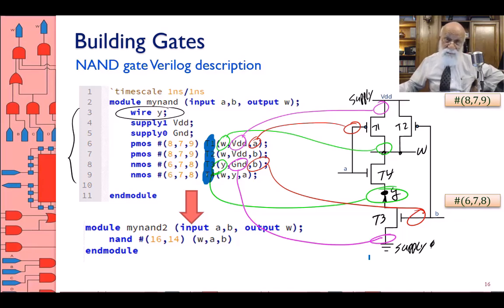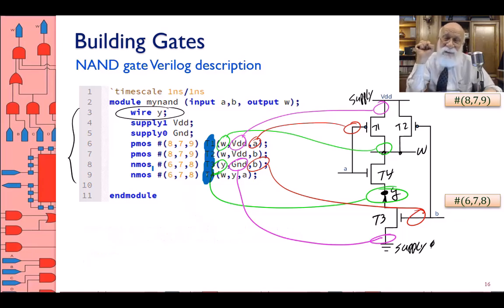And what I have up here is a very, very detailed description of the NAND structure. And it's good, actually, because when something changes, I see the Z's, I see the X's, I see all of these. But the problem with this description is that it has 1, 2, 3, 4 components. When there is an event on A, 4 components see this. 4 components have to react to a change on A.